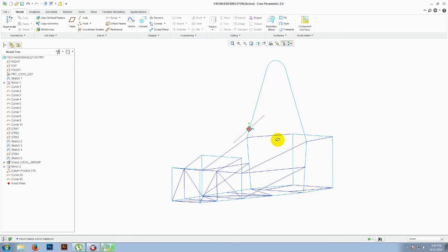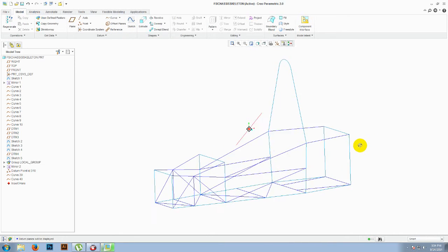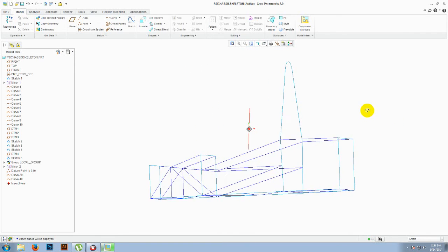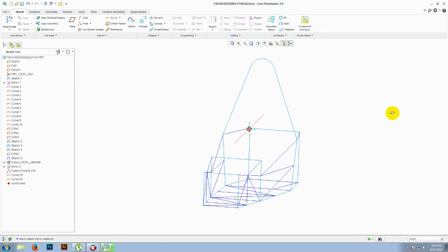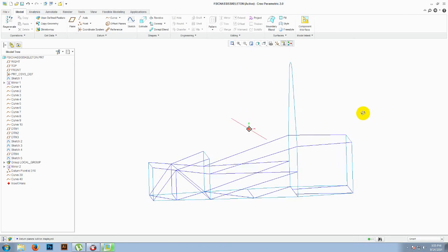The basic method is to create 2D and 3D curves. 2D curves can be created using the sketch option provided in Creo, and the 3D curves can be created using the curve through points option up here, or any option like a curve from equation or a curve from cross section. You could also use the style option, but some complex 3D curves are not supported in AFX, so be careful to use your options.